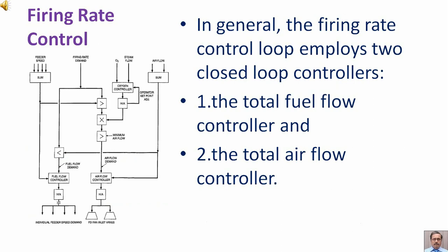In general, the firing rate control loop employs two closed loop controllers. First, the total fuel flow controller, and second, the total air flow controller.